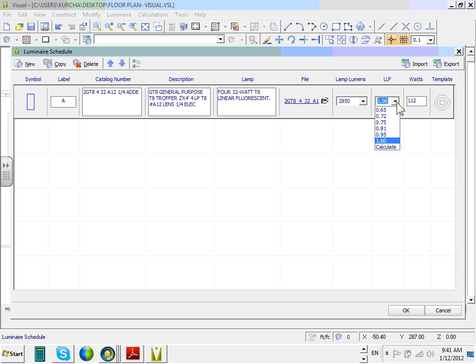The chemistry doesn't work, so it goes down. So the designers design based on longer term. So I think 0.8, pick 0.81 for the fluorescent lights. Typical for fluorescent light, this assumes that 19% of the fixture light is lost after a year or so, and it is going to go downhill from there.